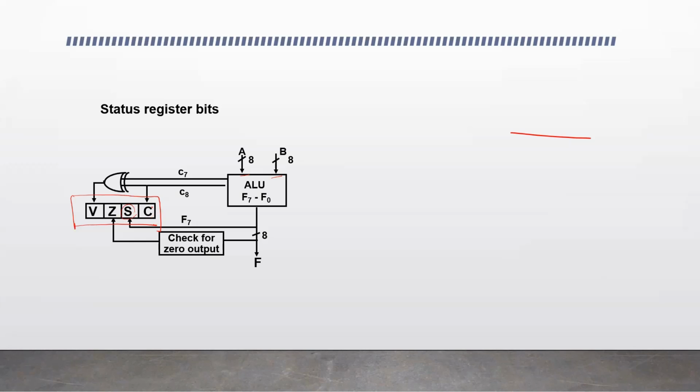Okay, here is if there is a carry. After the operation, this flag is used to indicate if there is a carry, and this flag is used to check if the number is positive or negative, the sign bit. And we have the third bit of the register indicates if the bits are all 0. So we have a zero flag here. And we have this V flag that is to check overflow condition after the operation, if there is an overflow.